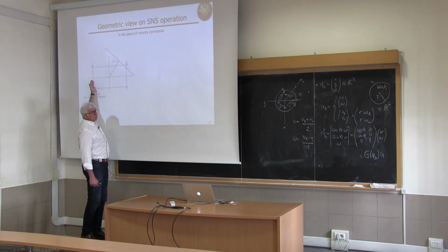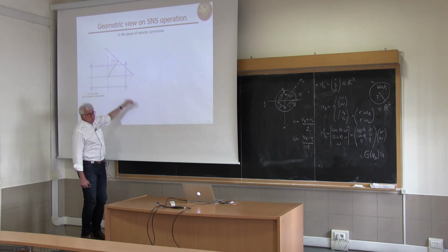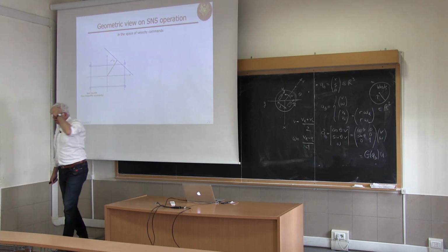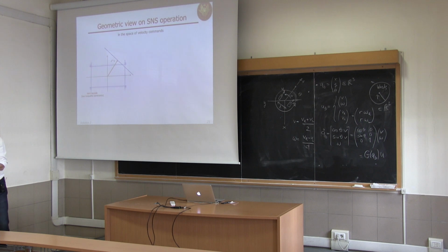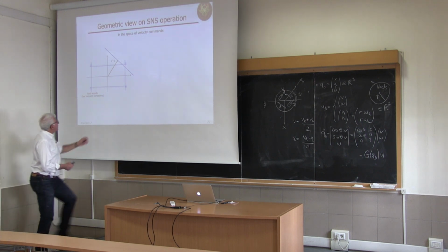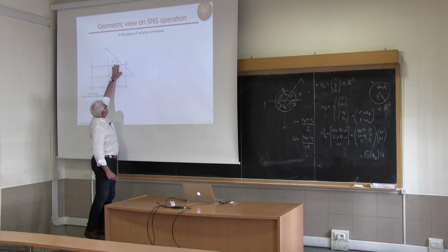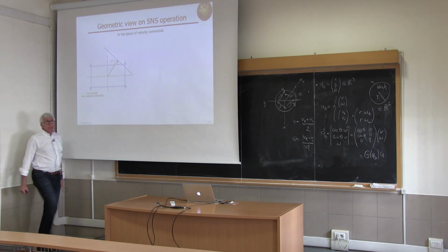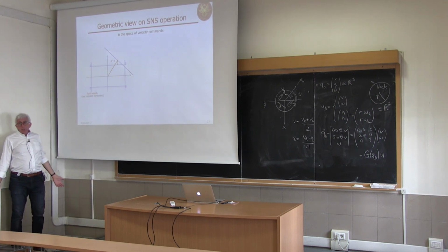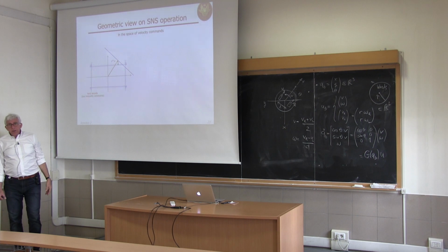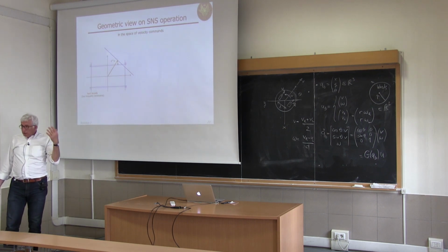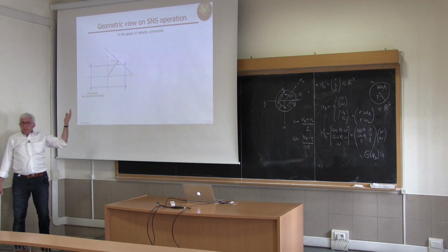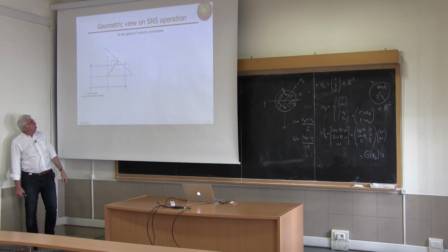So one constraint violated, the other not. So there's no choice to make here. We simply have to bring the Q2 dot velocity to the closest limit. This is overdriven, so we are bringing it to its saturated value. And of course, this solution is not yet correct because we have not moved Q1 dot, which was originally chosen as being the minimum norm solution on the equality.